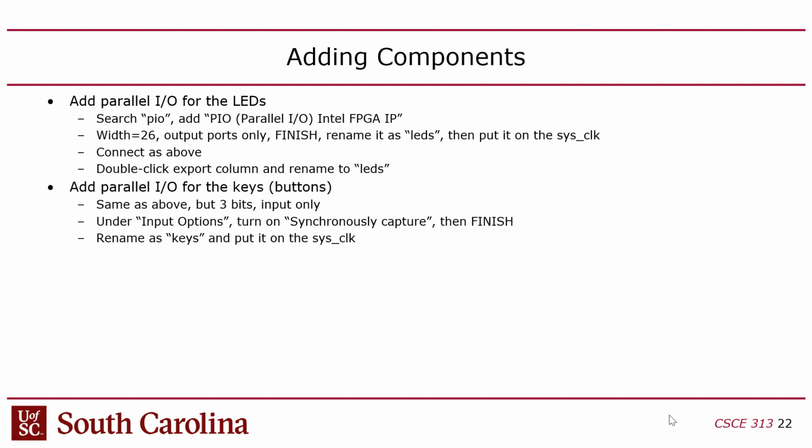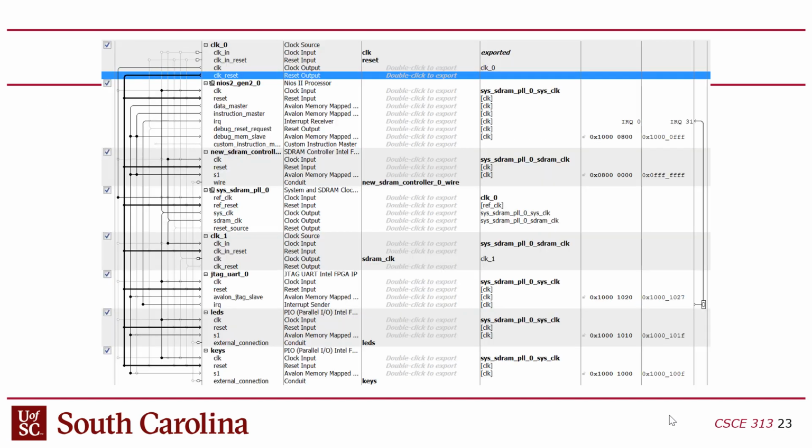But in this class, we're going to be doing both. We're going to do it in software first and then in hardware, right? When you do stuff like this in software, it's called bit banging, which means that you're writing code. Like we used to have a lab in the old version of this class where we did UART through bit banging. So you would write software on the Arduino to implement a UART channel, right? As opposed to using the hardware. But in this case, we're going to do it for PWM. Okay, any questions?